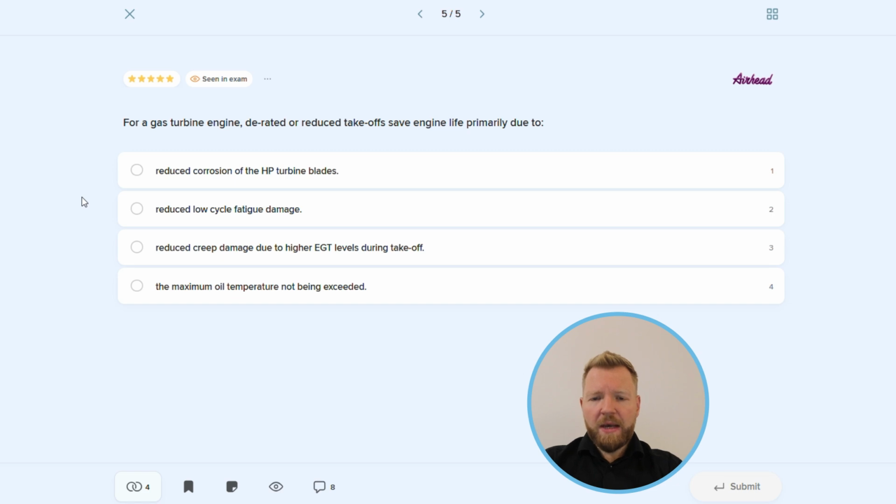The first one is called derated thrust. Pilot can set a predetermined lower maximum thrust for the engine through FMS CDU. The important consideration here is for the method that it can not be overridden by the thrust lever position alone. So, for example, in case of emergency, the full power of the engine is not available.